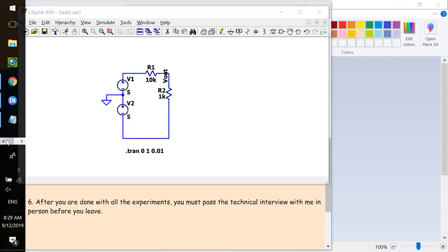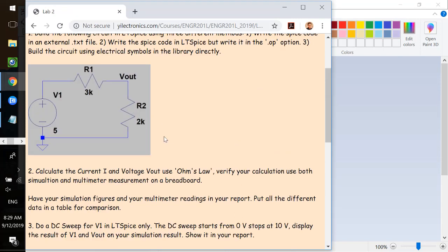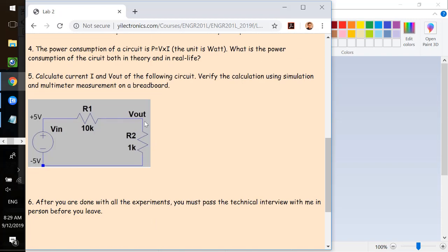Previously, you could do that because the voltage drop across this resistor equaled VL. But now it is not VL. What we want to get is actually VL, but if you directly use the voltage share, you are getting a drop across R2, not VL, right?